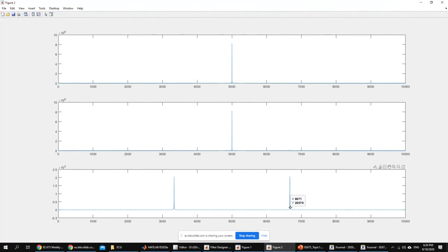Remember when we were talking about the estimation of the artifact, we were talking about estimating that from the actual signal using estimates of the frequency, whether it's lower or higher than the original signal, things of that sort. Here in the frequency domain, it pops up like this. Very clearly, you have the artifact at this particular frequency, here and here. So all you have to do is just zero out these two, just make these 0, okay? It's very simple. If you do that, you're going to end up with a completely clean signal.